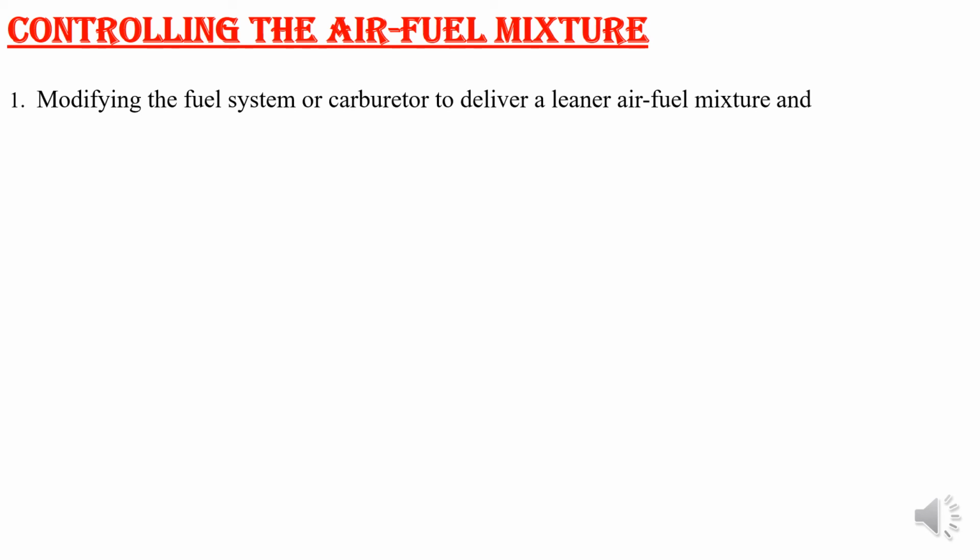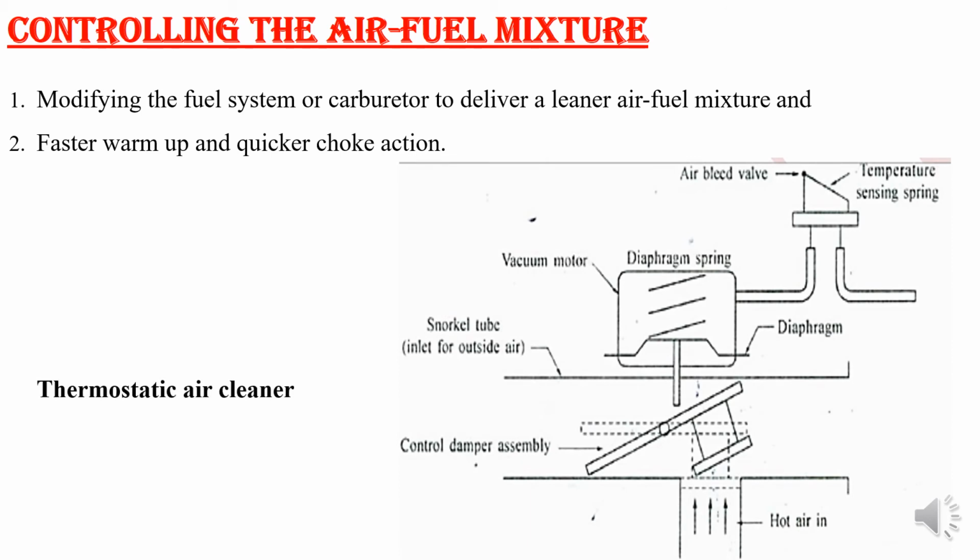Then the controlling of your air fuel mixture will be very much needed so that you can control your emission, modifying the fuel system from carburetor. Now the carburetor has vanished and the fuel injector is placed, so that emissions are much more in a controlled way. Then the faster warm up will be there. So this one will be your thermostatic air cleaner. In the thermostatic air cleaner,